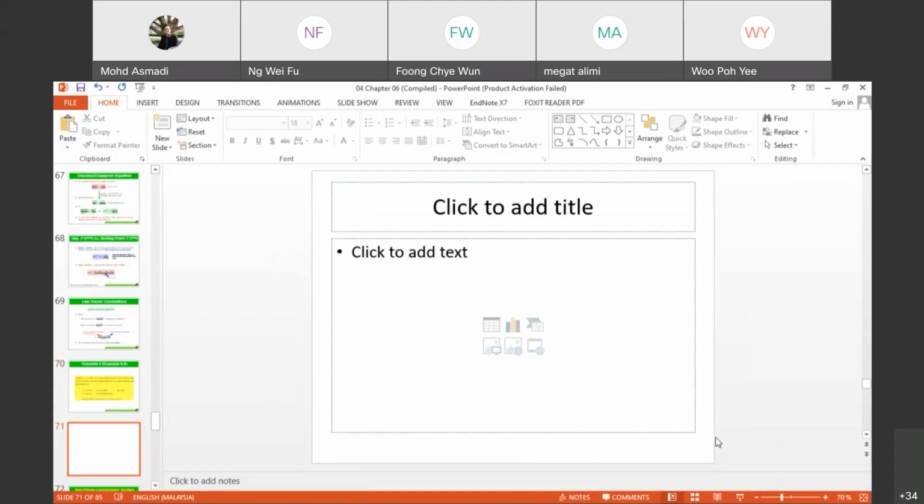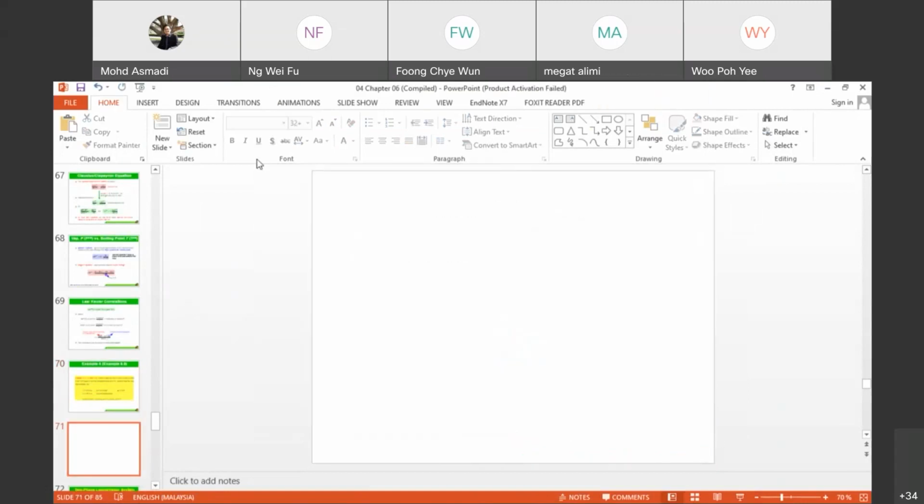If you look here, the first condition is saturated liquid, and then the final condition is the gas. Please remember, understand the phase. Please determine the phase, initial and final, as well as construct the hypothetical path. If the entry is vapor and the exit is vapor, it is easy.